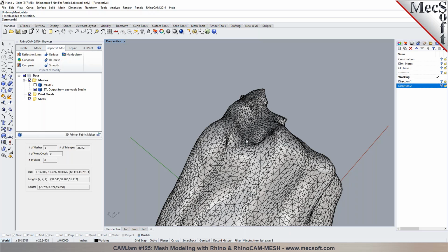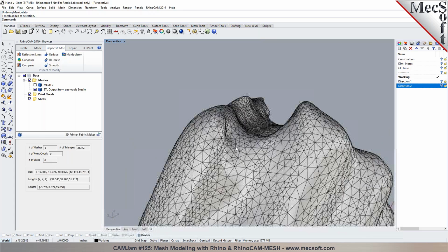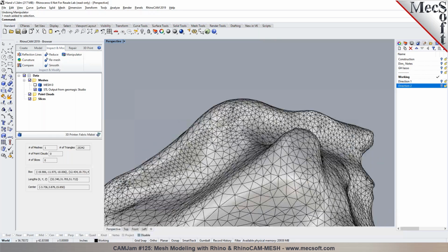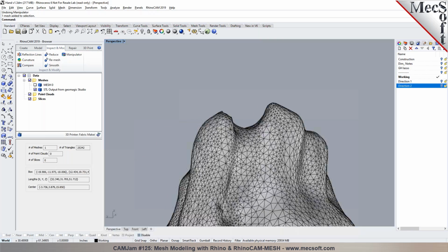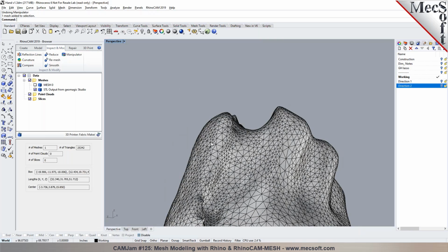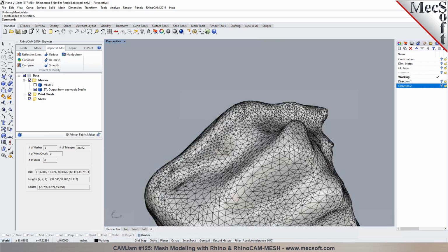I could do that, but what might work better is if you draw something in Rhino and you can blend that to this model itself. So, for example, if you draw a few curves, and then you can make a NURBs, right? Make it a NURBs, and then you can even make it like a pipe or a solid. And then once you do that, you can convert that to a mesh. So, for example, in Rhino, you can take a few points and you can basically build that into this mesh.